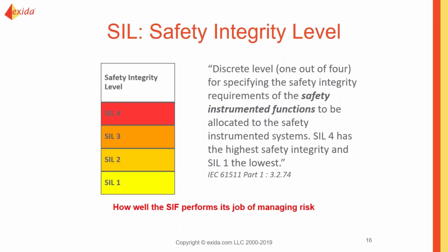One thing to note is IEC 61508 defines all 4 safety integrity levels, while IEC 61511 only talks about 3. That's because IEC 61511 is more geared towards the end users and process safety. And really, SIL 4 is not used in the process safety sector, except in rare situations such as nuclear or some rail applications.